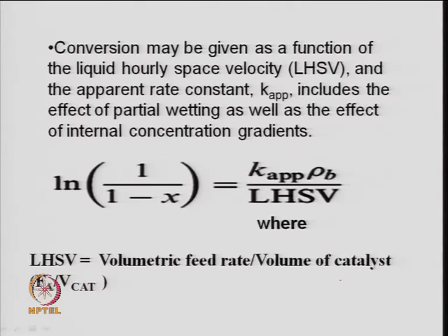So, the expression has been shown, what we have discussed earlier. So, I am not going into this form. Sometimes we call it liquid hourly space velocity. Liquid hourly space velocity is related to the volume of the catalyst in the bed and the volumetric feed rate.